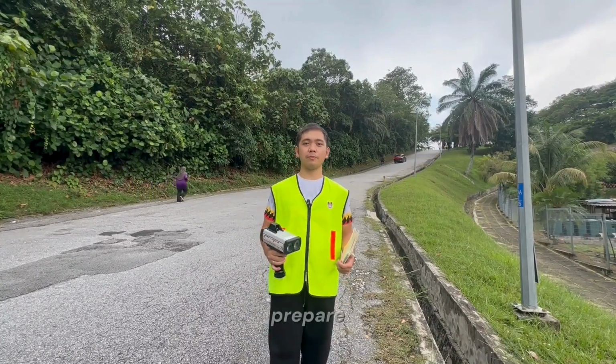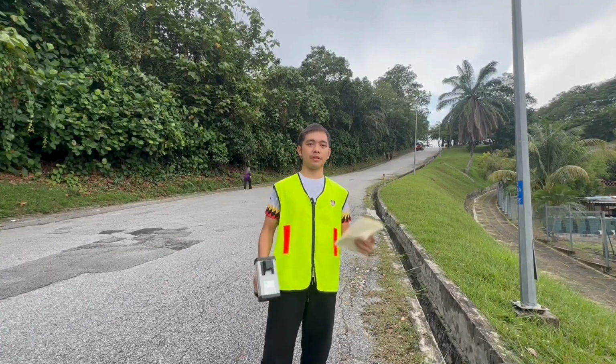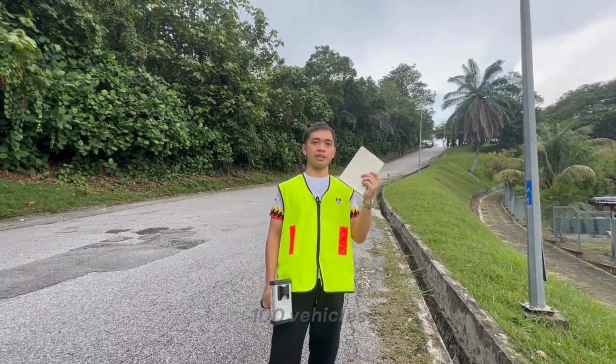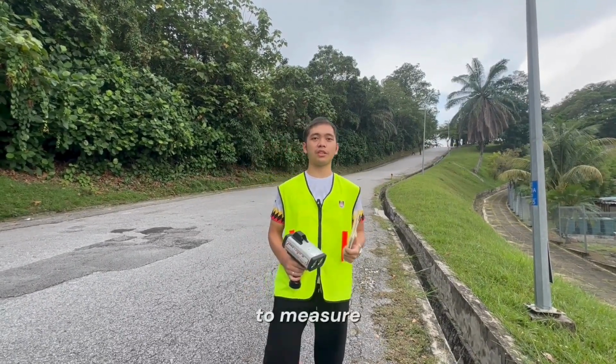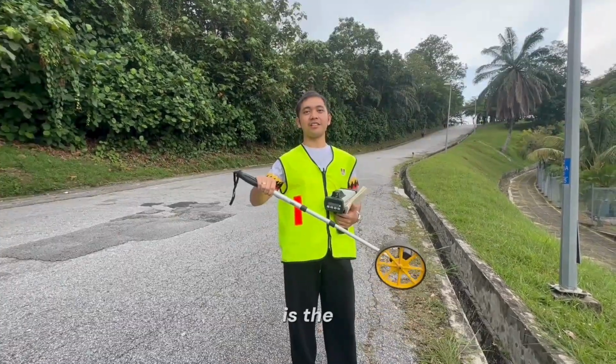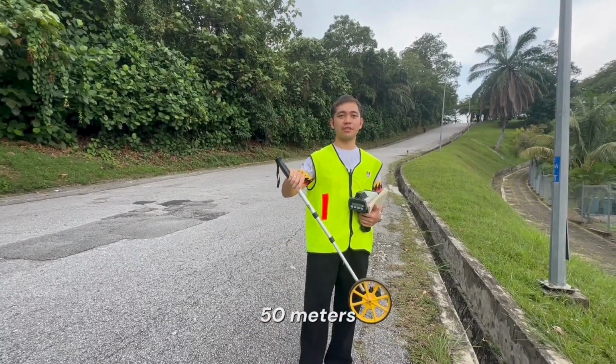For this test, we need to prepare first. The apparatus is a safety vest. Secondly, a radar gun to measure the speed. And this is the data sheet to record all the speed data, which is 100 vehicles. Next is a stopwatch to measure the time, which is 1 hour. And this is the measuring wheel used to measure from point A to point B, which is 50 meters.